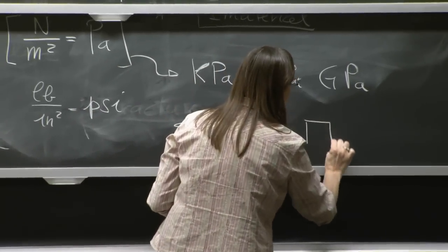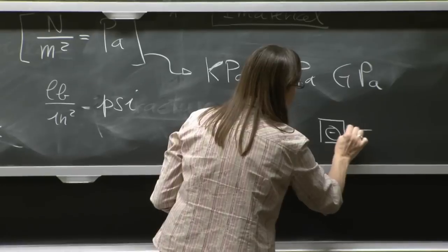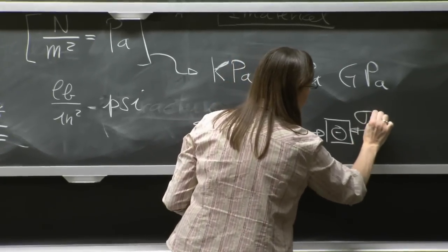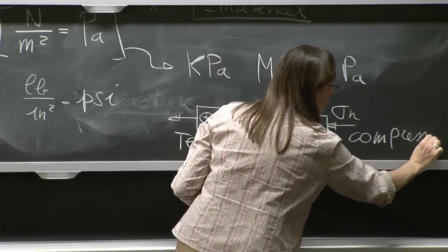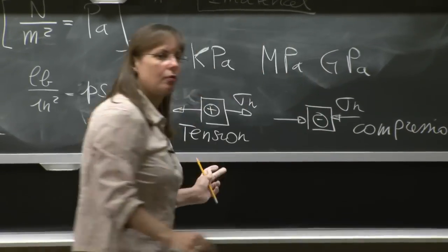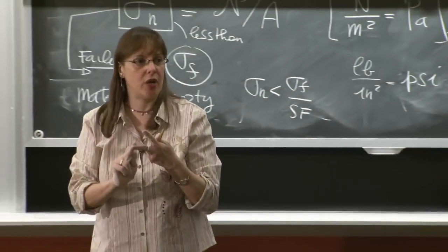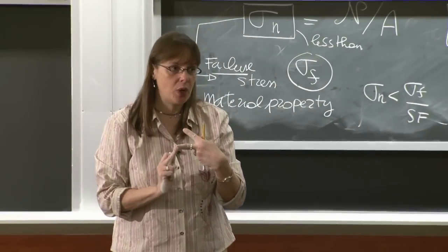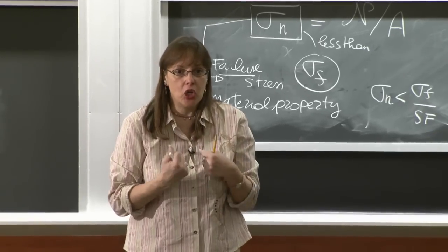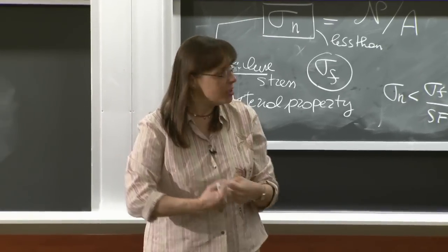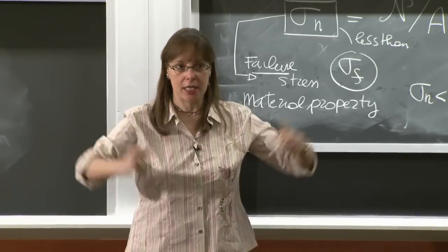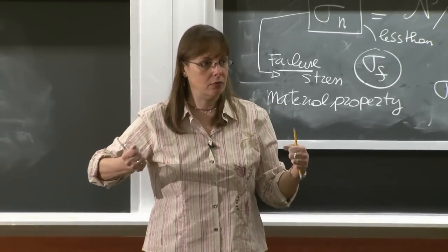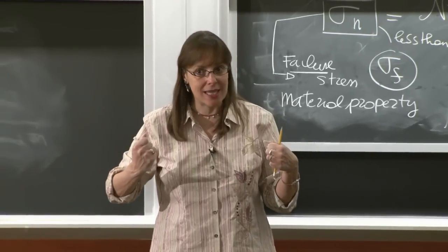And a negative stress goes with compression. You see, stress and strain do not care which way the x-axis goes. Go with what the structure feels, tension or compression, and with what happens to the structure. Gets longer, gets shorter. Okay? You measure what's inside.